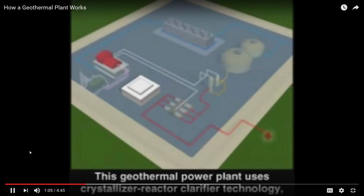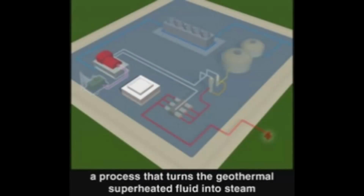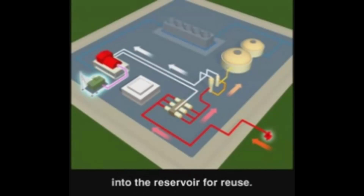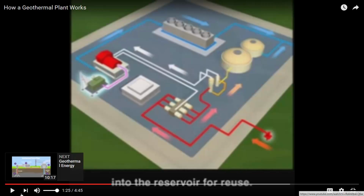This geothermal power plant uses crystallizer reactor clarifier technology, a process that turns the geothermal superheated fluid into steam while removing solids from it. The steam is used to drive a turbine and generate electricity. All remaining geothermal fluids are injected back into the reservoir for reuse. So here's where we diminish that issue that they had with depletion of the reservoir or the fluids, the reinjection into the reservoir for reuse.